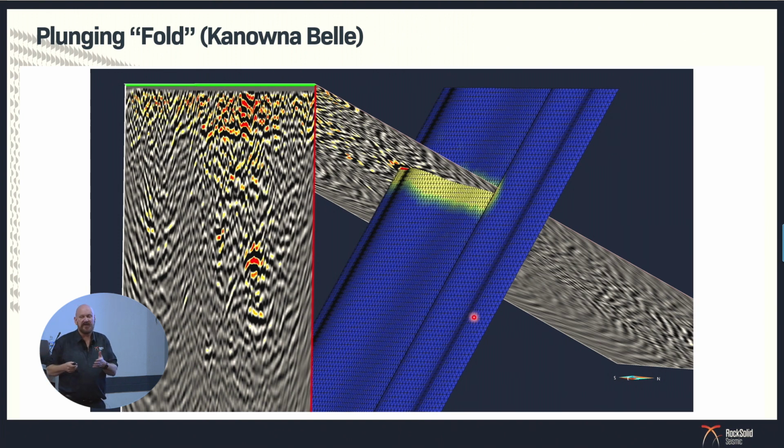So the best way to overcome that is survey design. Yeah, you put your line in here, but you also put one across it. Because if we'd put one perpendicular to that, we would have seen that these things were dipping, plunging at 60 degrees or more in that direction. So ideally, you put a dip direction line and a strike direction line in, or perpendicular to the dip direction. That's how you should design your 2D seismic data sets.